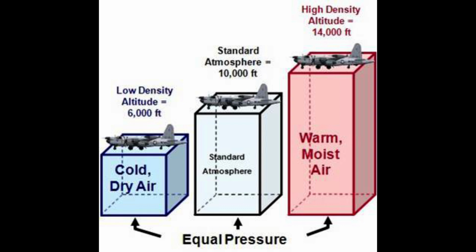However, a known density occurs for any one temperature and pressure altitude. The density of the air has a pronounced effect on aircraft and engine performance. Regardless of the actual altitude of the aircraft, it will perform as though it were operating at an altitude equal to the existing density altitude.